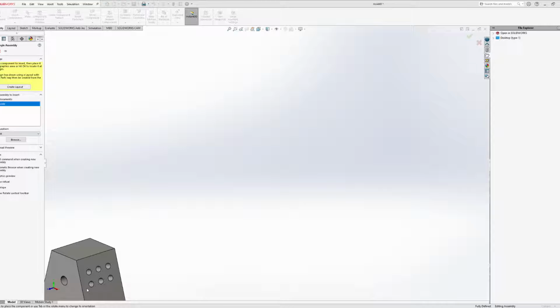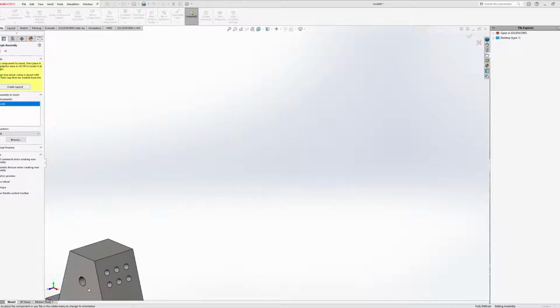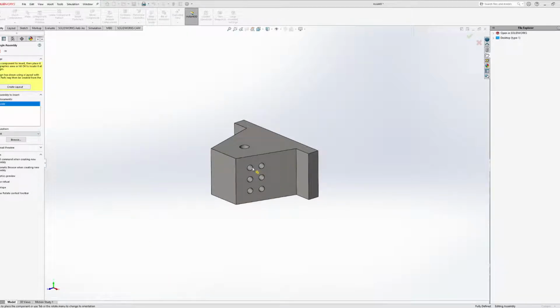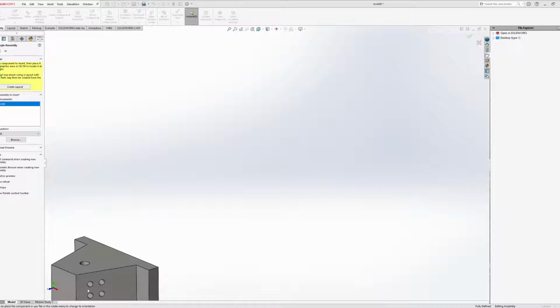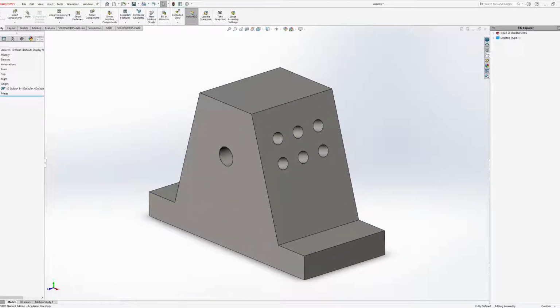So if I hit X, it's going to rotate it in this manner, if you guys were able to see my mouse. So this orientation that it just created should come as no surprise. And I can just hit it a couple more times to get back to its original orientation right there. Now I'm going to left click just so I can insert that component.